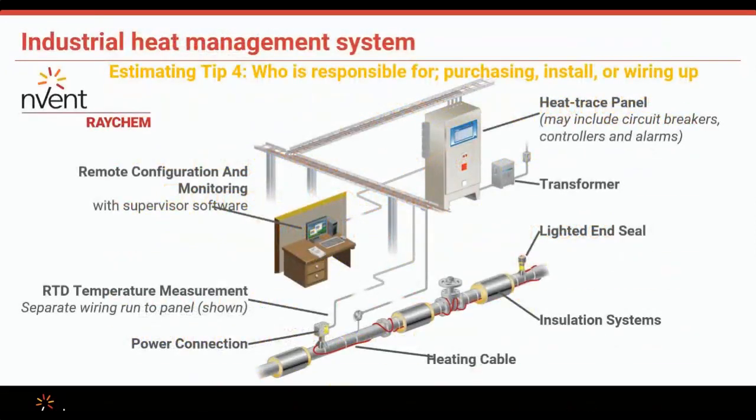All right, estimating tip number 4. So who is responsible for purchasing this? Who's responsible for the installation or the wiring of this? There's a lot of parts and pieces and components to this heat trace system. And you have to be cognizant of where it's called out for in the spec, what their notes say in a project that's a designed project. So be sure to ask those questions.